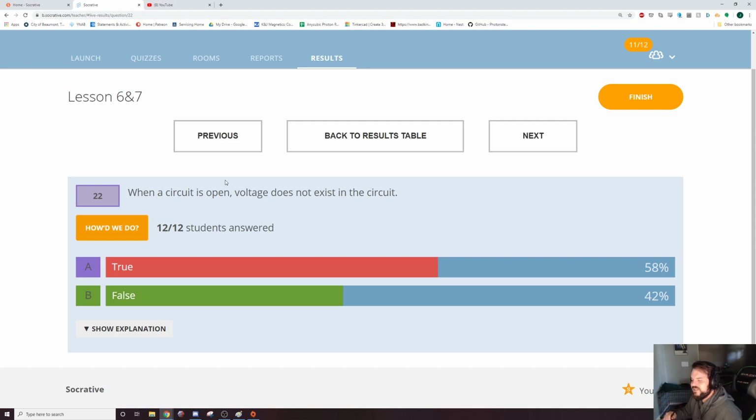Actually, you could argue that there's... I'm not going to go there. You can read the voltage across a switch whenever it's open. You read across the screws on a switch, and it'll tell you how much voltage is trying to get across that switch. Voltage is just a potential. Whenever you're trying to read in the circuit, voltage is the potential. That's all you get.